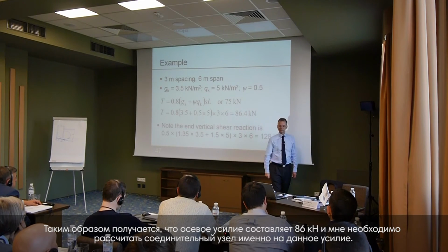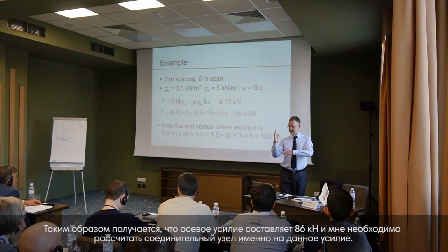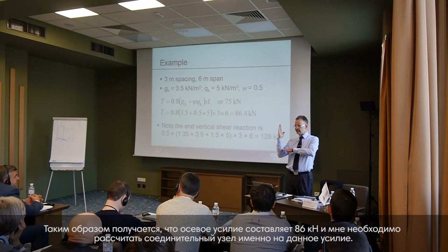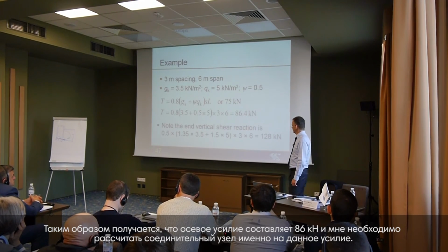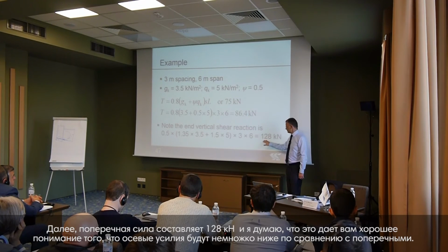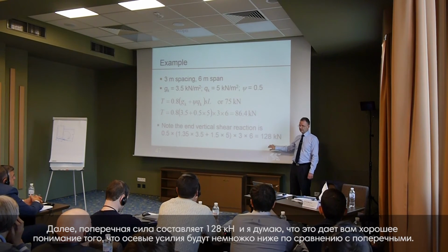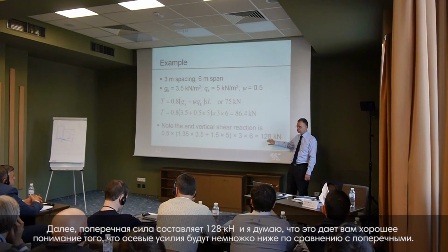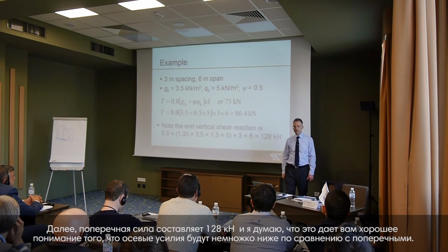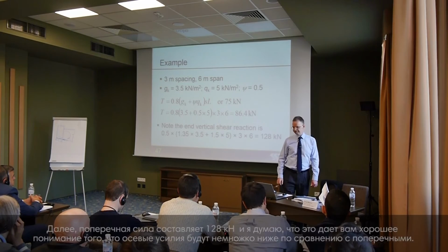So my tying force is 86 kilonewtons. So I would need to verify the connection for 86 kilonewtons. Notice that the vertical shear is 128 kilonewtons, so I hope that gives you a reasonable idea that the tying force is a little bit less than the vertical shear force.